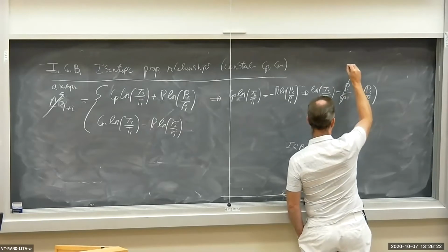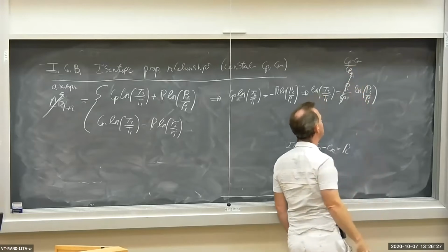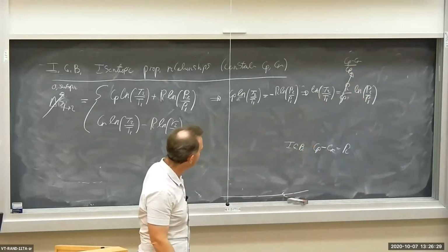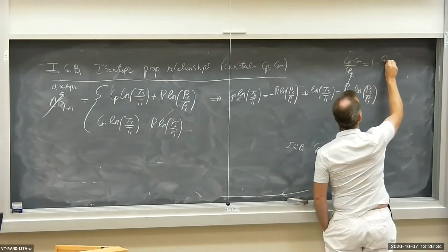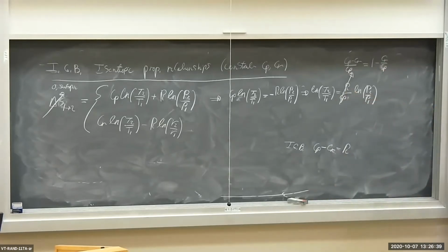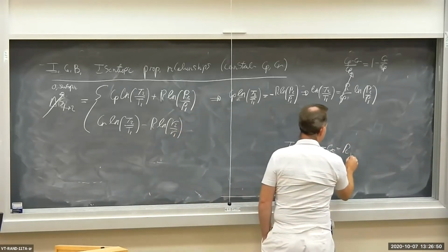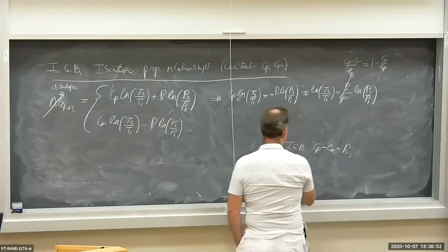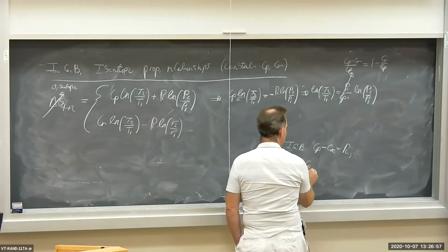So I'm going to make a substitution for R here. We get Cp minus Cv over Cp. That's what that ratio is, R over Cp. And that gives me 1 minus Cv over Cp, which is 1 minus 1 over Cp over Cv. Now, Cp over Cv, I only mentioned this one time. There's a quantity k. k is referred to as the ratio Cp over Cv.